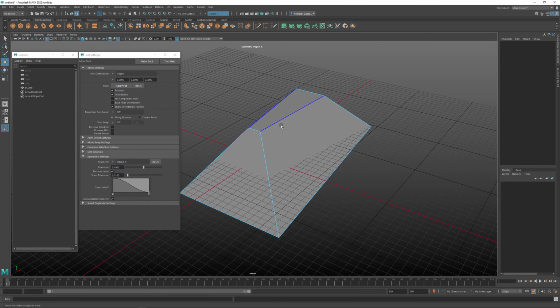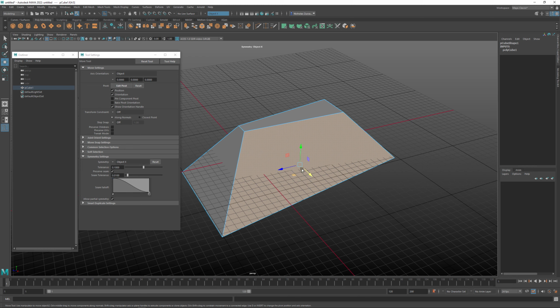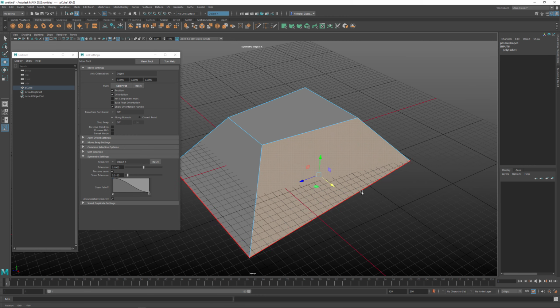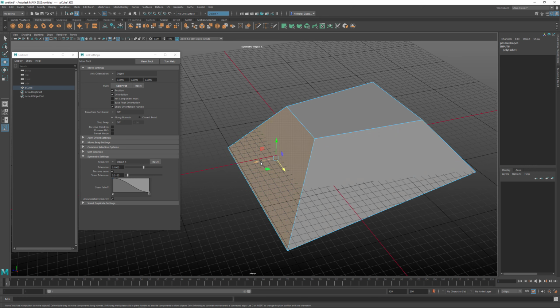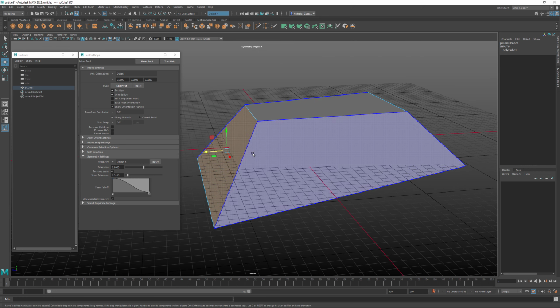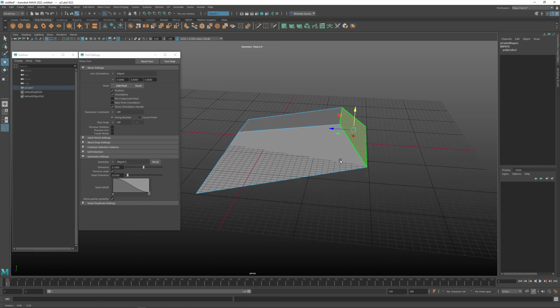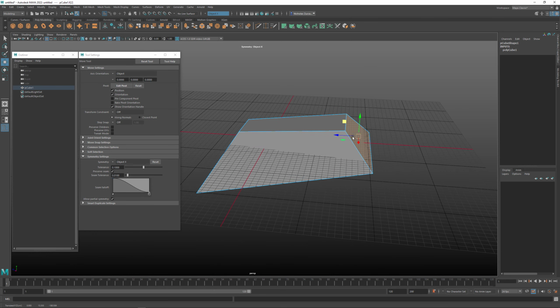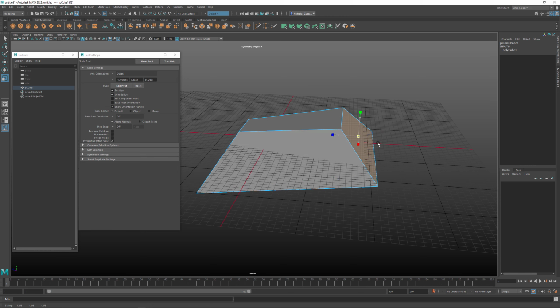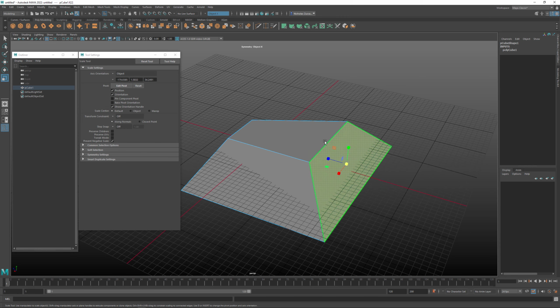And then the next level that we're going to go to is if we right click over this and say face, we can move a face. Now moving a face is basically whatever this face touches, it's touching these edges and these verts. So it's like it's moving this entire mass all at one time. So it's going from the smaller to like medium, and I would say edges, you could think of them as medium, and then faces is like large forms that you're moving around. And then the largest form of all is the object mode that we would work in for that.